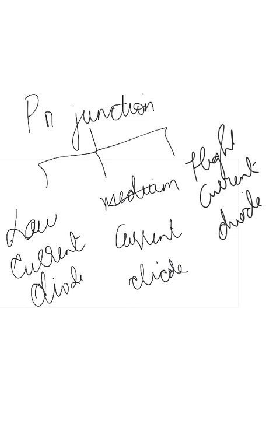What do you mean by low current diode? The low current diode means the diode is capable of passing a maximum current of up to 100 milliamp and withstanding 75 volt reverse bias without breakdown. Coming to the medium current diode, the diode can pass a forward current of 400 milliamp and a reverse bias of 200 volt.